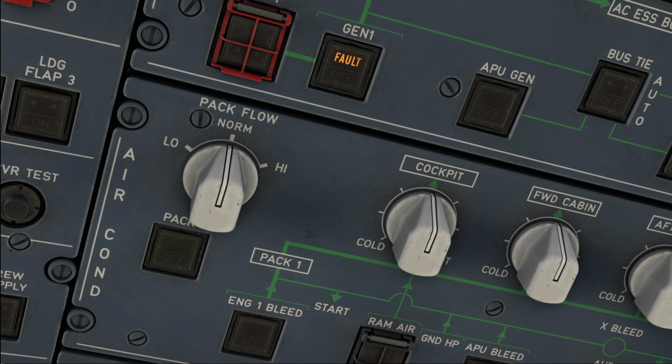Now, this saves approximately 0.5% of the trip fuel, but living in a time where we are paying about $1,800 per ton of fuel now, this can make up quite a difference. Another airline, for example, uses pack flow low for up to 85 passengers in the A319 and A320, while they use also 140 for pack flow ECON on the A321.